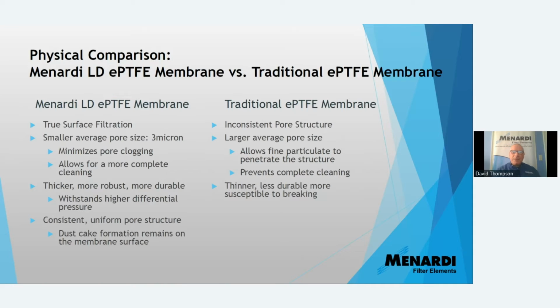which had a very inconsistent surface and pore structure, in that it allowed particulate to penetrate into the deep matrix of the material and the tortuous path, get stuck in there, and over time, as the media was pulsed and cleaned and then brought back online again, more small particulate would get trapped, and eventually the differential pressure would rise. The run times, the duration between pulses, would be shorter, and you would end up pulsing more frequently, thus creating more stress on the media and beginning to wear the bags from the inside out.